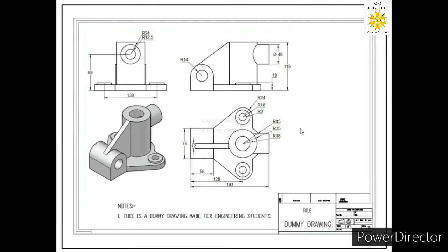So whenever we have to convey the design to the manufacturer, or whenever we have to prepare engineering drawing, primary drawings will be orthographic projections only. But in order to assist those orthographic projections, we give one more drawing that is called as isometric projection. And we add these projections when we feel that the geometry of the object is complex and reader may get confused while reading the orthographic projections. So in order to assist the reader, we give one more drawing which helps the reader to understand the overall geometry of the object. Now let us understand about these isometric projections in detail.